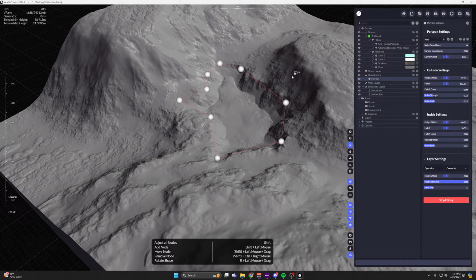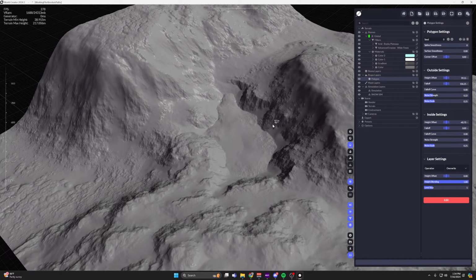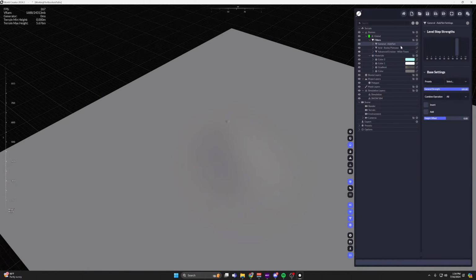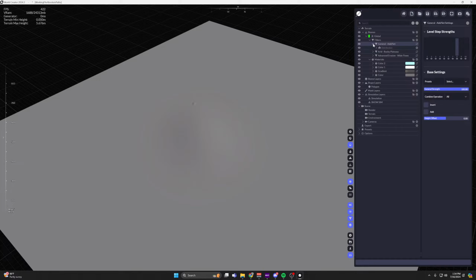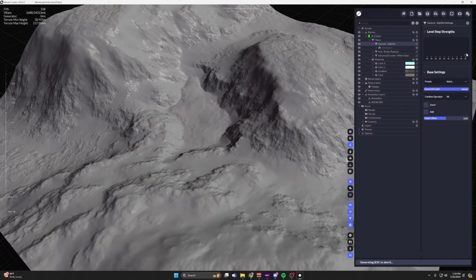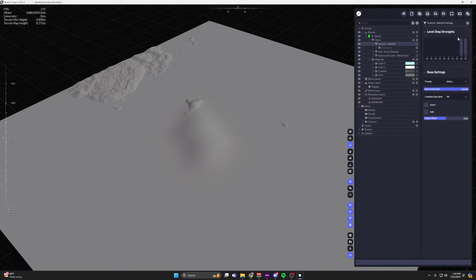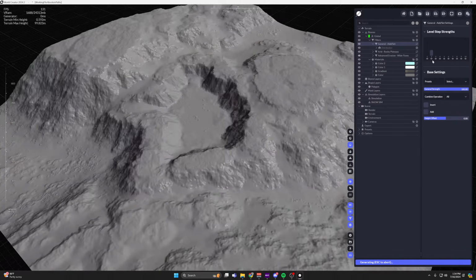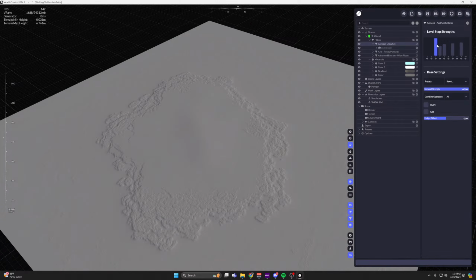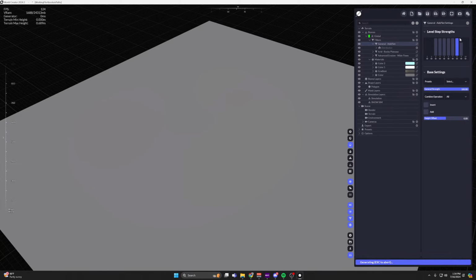How can I flatten specific areas? All right, so if you want, you can add a filter, add set. And let's say for the distribution of this, we want it to be all the way. So add set's really cool for the distribution. If we were to choose a layer, we can either do it based on a mask, or in this case, I'm going to do it based on that polygon that I just made.